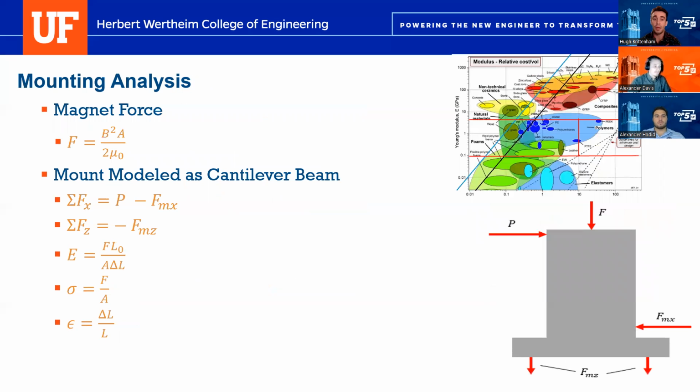For the optic mount, the material was selected using an Ashby plot analysis. We utilized a clipping system, which became the main requirement for narrowing down our material selection. After analysis, it was found that a polypropylene copolymer proved to be the most optimal material based upon the durability and its low cost. The average weight of the optics components is extremely low, about 100 grams, providing no serious force canting the mounts downward.